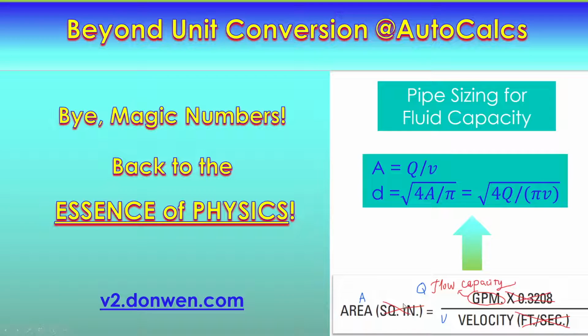You can see traditional people use this kind of equation, which is specific to a specific unit. Like this one, based on the flow capacity, the area of the pipe equals the GPM, which is actually the flow capacity, divided by the velocity V. But because of the specific units, it comes with this magic number, like here it is 0.3208.